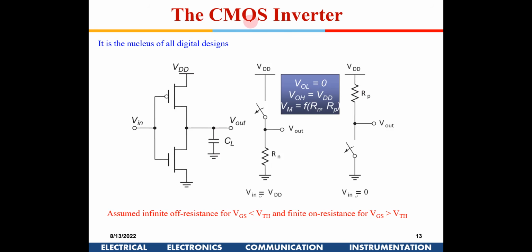So this is the CMOS characteristics curve, where instead of resistance, I have a PMOS here. If you see here, when V in is high, this transistor is switched off, and I just have a channel resistance here. So whatever is the output gets connected to the ground, so there will be an effective R through which the capacitance gets discharged completely. So I have VOL equal to 0.